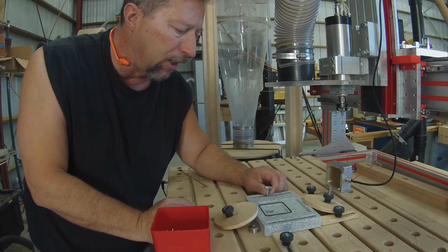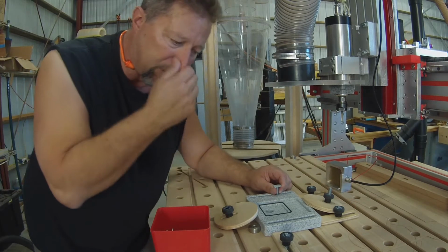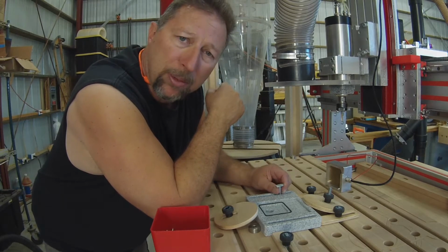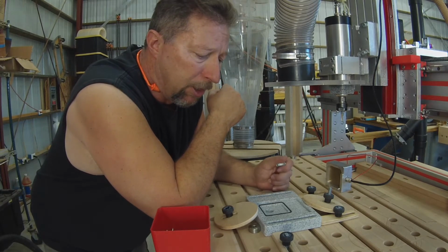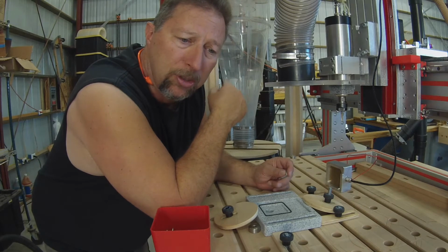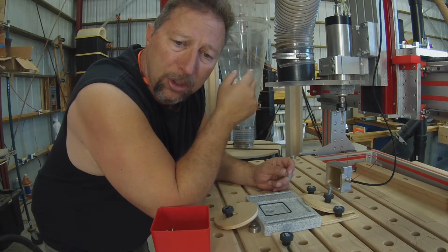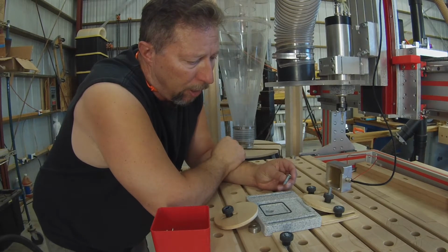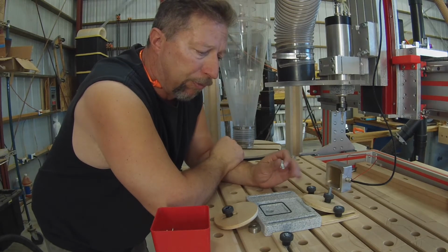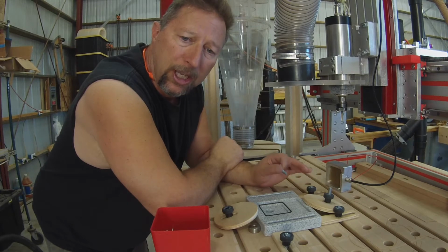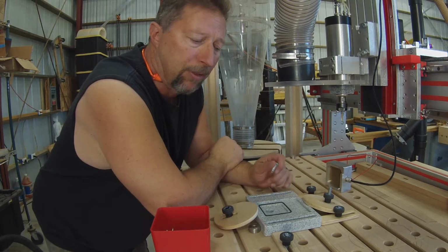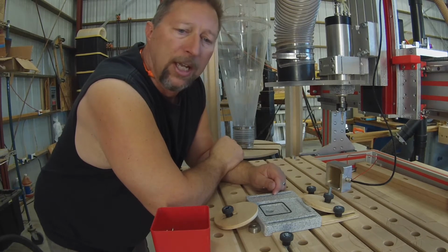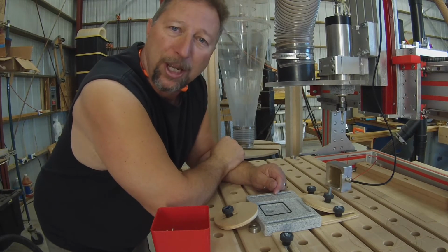It's very tight. And it turns out that what I did was when I made these slots, I forgot to double check the width they need to be. I originally programmed it at 8 millimeters, and on my other jigs I programmed it at 9 millimeters just to give me enough slop to get the bolt through clearly. So I had meant to go back before I removed the jig and its stock from the clamping fixture. I had intended to go back and modify the program and rerun it on just the slots. And in the excitement of being on camera, I forgot about that.